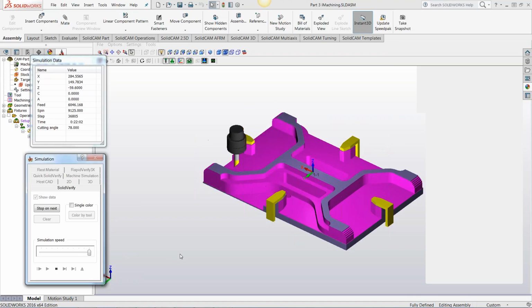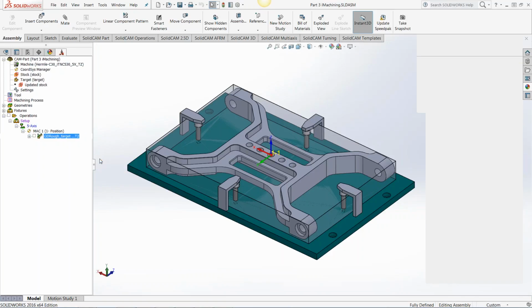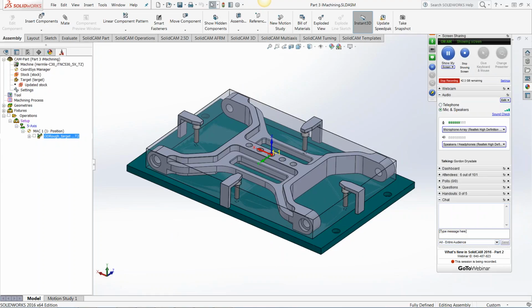So what you would do next, obviously, is move your clamps or put the clamps somewhere else, and then just run an iMachining operation a second time, an iMachining 3D operation that is, and it will only machine the material that's been left behind by where the clamps used to be. So that's an excellent addition, I think, to iMachining 3D.